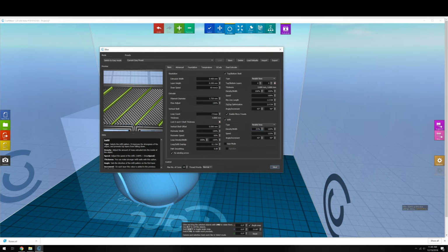The next box gives you the density of the fill. So 100% fill would be a solid object, and a 0% fill would be a completely hollow object. Both of these are extremely impractical, as a 100% solid object would take way too much material and way too much print time, and an object with zero infill would collapse on itself and could not have a surface. Typically, you will use anywhere between 15 and 25%, depending on how sturdy you need your model to be.